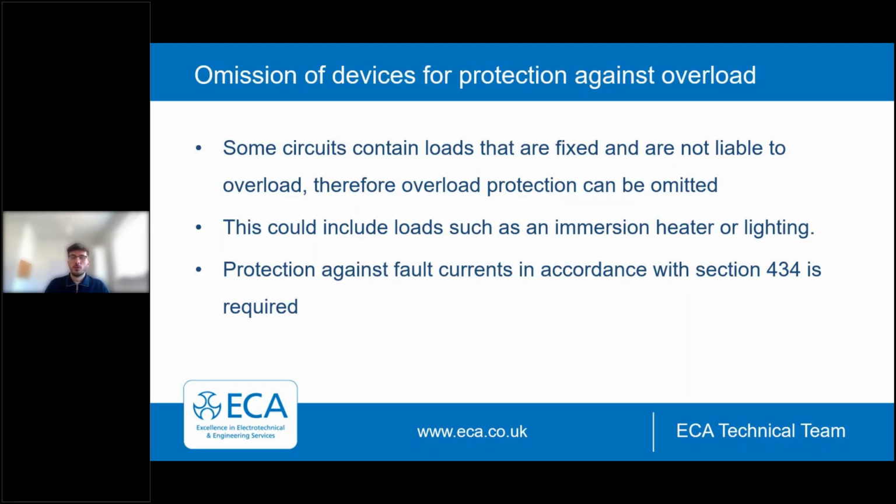So again, we would need to ensure that for the circuit, although it may not be protected against overload, due to there being no chance of an overload happening, we would need to confirm that if a fault condition was to happen, so for example, a short circuit, that the conductors could safely deal with the level of fault current flowing through the conductors for the required time for the protective device to operate. So the cables don't get thermally damaged.